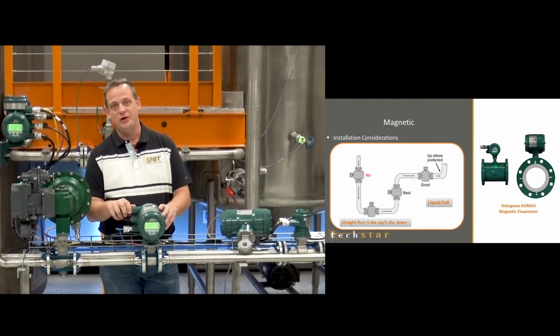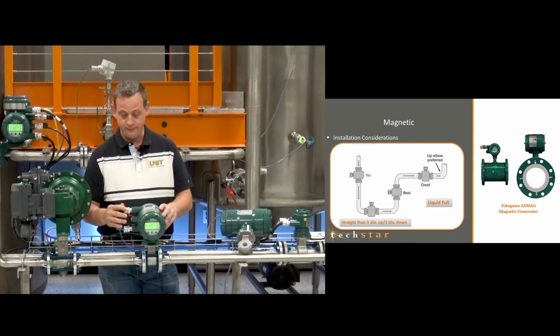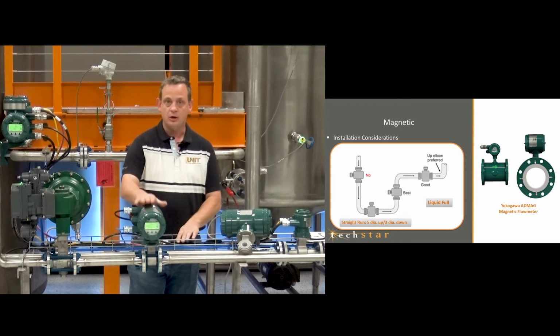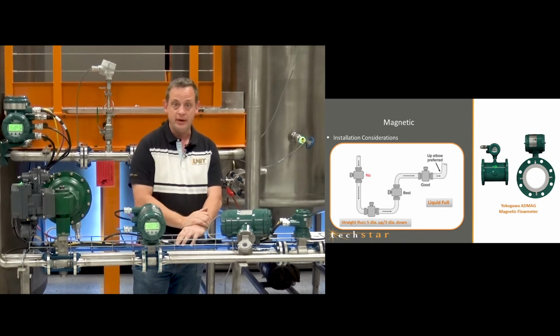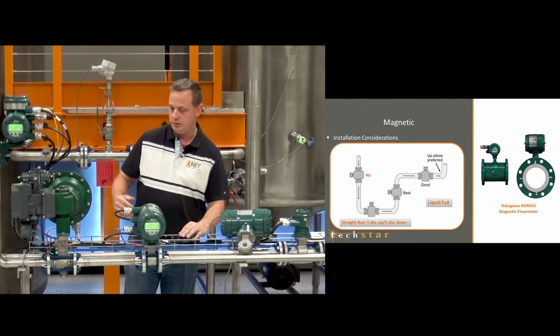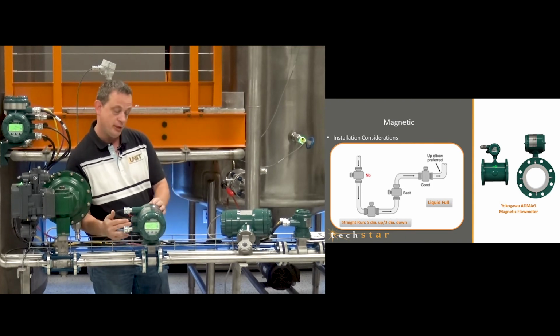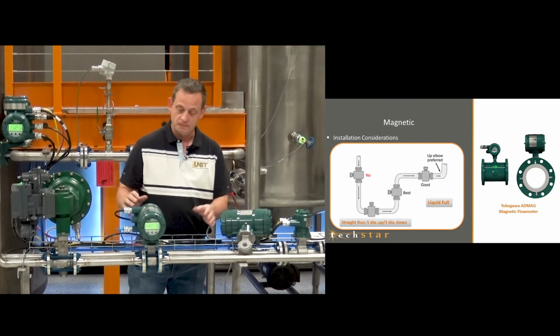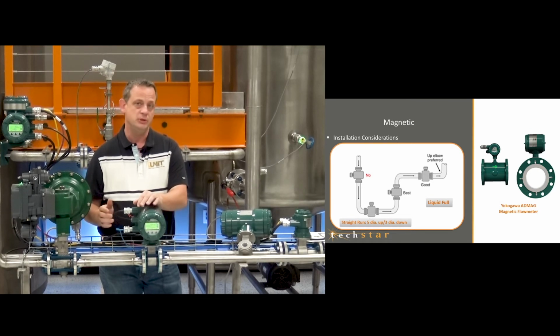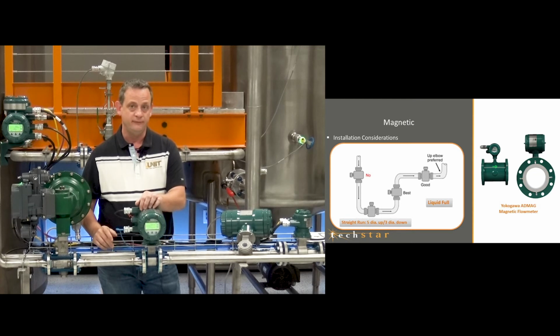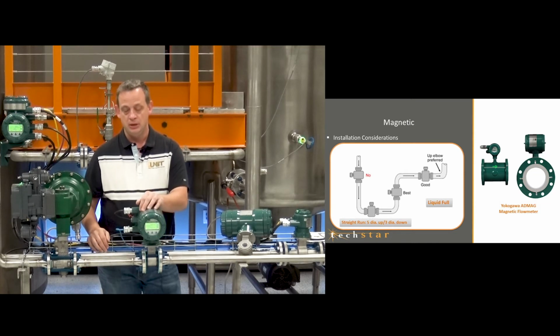okay. All right, guys, so now we're talking about the mag meter. This is the magnetic flow meter, and a couple of installation guidelines on this are going to be your upstream and your downstream pipe diameters. Upstream being flows coming this way, this will be upstream and then downstream this way. Recommended really depends on the manufacturer, but on some of your magnetic flow meters it's like 5 and 3. I've also heard 10 upstream, 5 downstream is also very common. It depends on installation around valves.